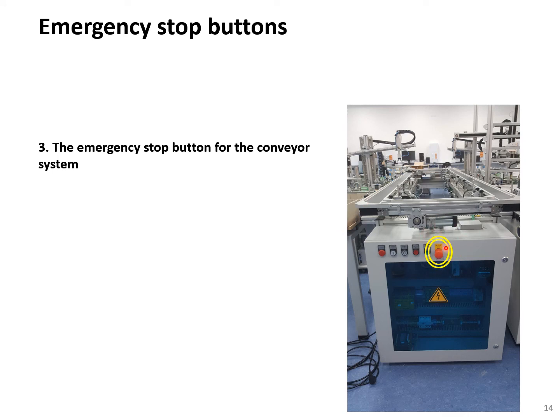If you press any of the emergency stop buttons on this MPS 500 specifically, it will shut down the whole system, which is okay. But in different factories, those emergency buttons could be dedicated to a specific line or a section of the company, and you should be aware of what part of the manufacturing line is under the control of that emergency button.